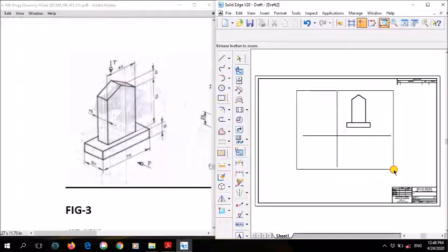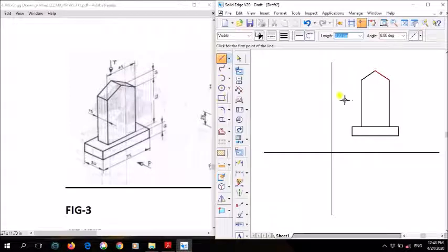Now I'll just zoom this part. We have drawn the front view. Now we'll draw the right view. Whether you see the object from the left or right, the view you get will be the same because it is a symmetric object, right? When you are seeing from the right side, this face is visible here, and this plane is visible here, as well as this. This slant is visible like a rectangle. When you are seeing from the side, whatever the angle is, this slant part will not look like a slant, but like a smaller rectangle like this. We'll draw this first part, then the second, and then finally this one.